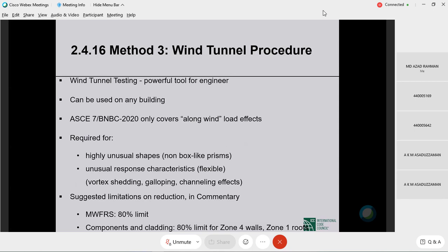Most of the time, any building in Chicago exceeding maybe 20 stories, which is much, is designed based on wind tunnel testing. Simply because you get to design the building for lower pressure than you will calculate out of ASCE 7. It is a fact. Okay. And in one of the slides, we tell you why that is so, why wind tunnel test pressures come out to be lower than the ASCE 7 pressures. But that is a huge motivation for doing wind tunnel testing.